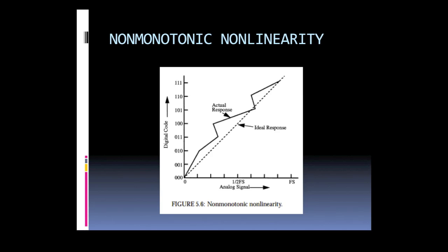Settling time for D to A converters is the time taken from a change of the digital code to the point at which the analog output settles within some tolerance around the final value. Glitches may also occur during changes in the output at major transitions such as 1 MSB or half MSB. During large changes, switching time delays between internal signal paths can cause a spike in the output. The weight of these errors is heavily dependent on the choice of converter architecture.